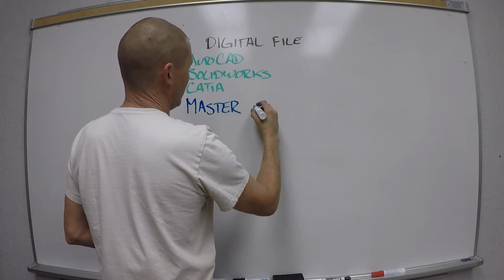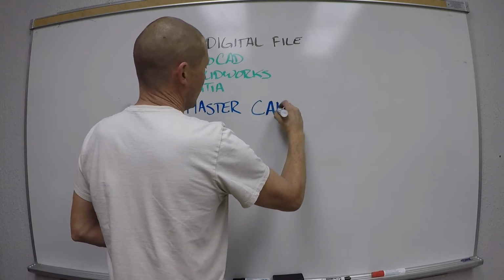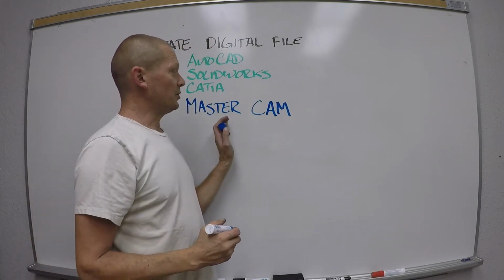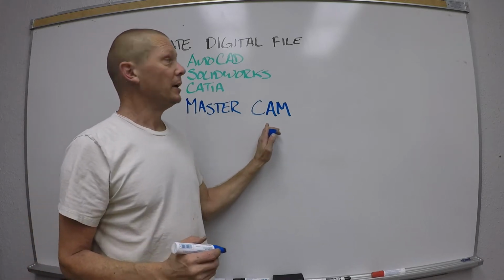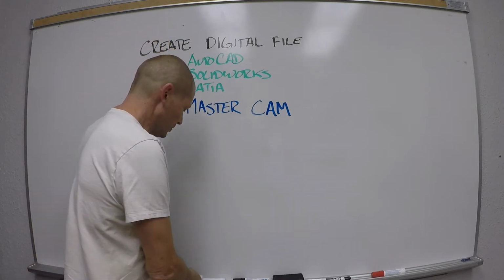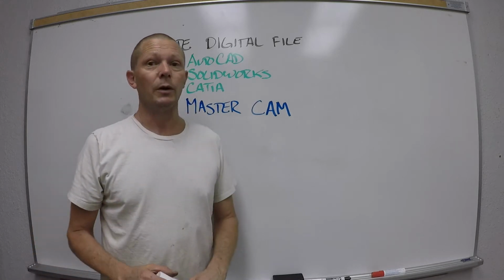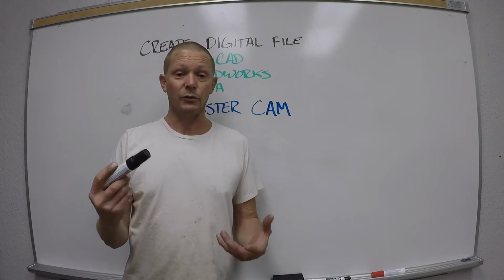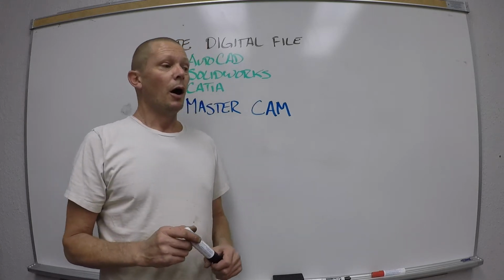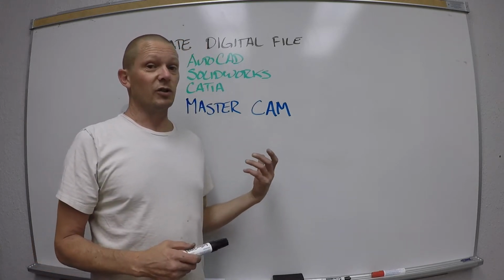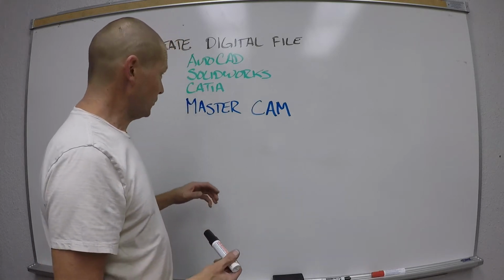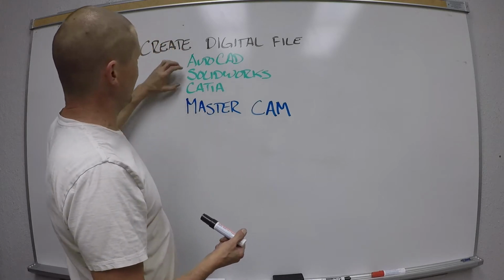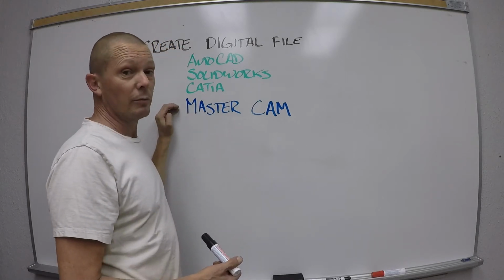What is Mastercam? Mastercam is software that is used to program your toolpaths for you, like drilling holes and cutting contours and profiles and pockets. And then it also generates the G code for you. You can also draw in it, and you could skip these three and just draw your part in Mastercam too.